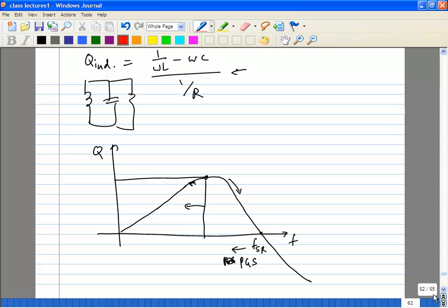You will find a few cases where you would end up matching to 50 ohms, in case of impedance matching. But there we are already assuming lumped element matching. You are already assuming you're using lumped elements to interface with distributed elements. A lumped L and a lumped C of certain values will transform the impedances from 50 ohms to 200 ohms. So there is no problem in using lumped element models.